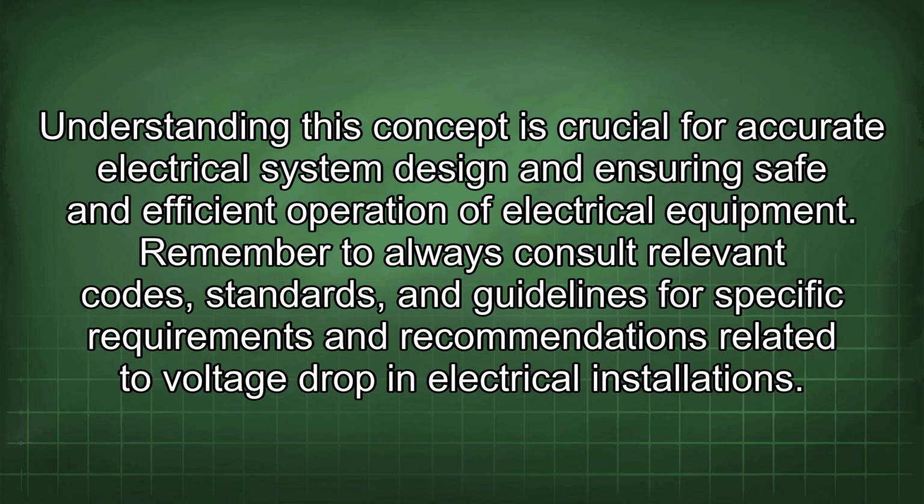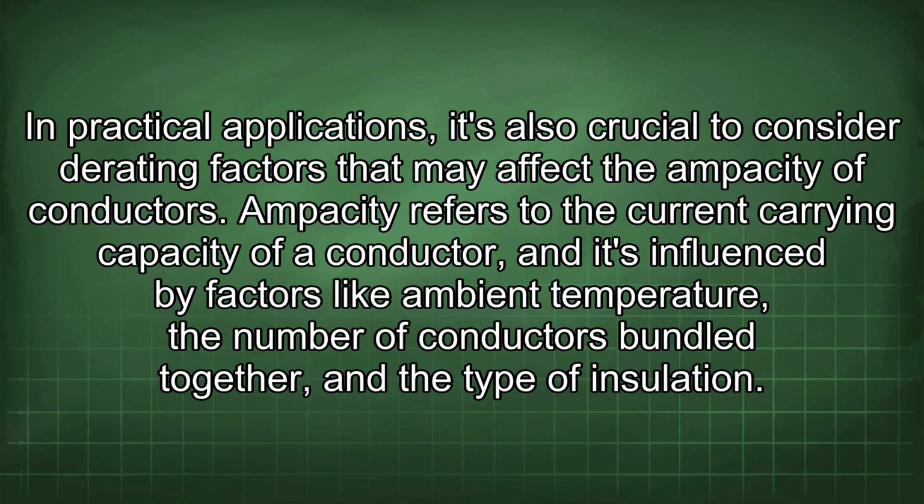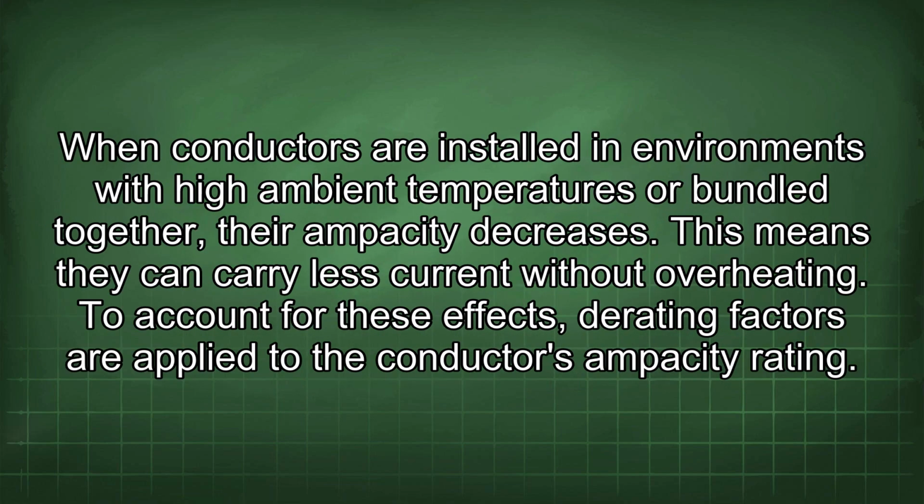Remember to always consult relevant codes, standards, and guidelines for specific requirements and recommendations related to voltage drop in electrical installations. In practical applications, it's also crucial to consider derating factors that may affect the ampacity of conductors. Ampacity refers to the current carrying capacity of a conductor, and it's influenced by factors like ambient temperature, the number of conductors bundled together, and the type of insulation. When conductors are installed in environments with high ambient temperatures or bundled together, their ampacity decreases. This means they can carry less current without overheating.